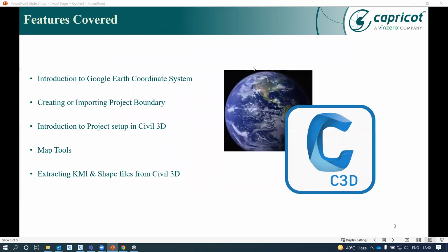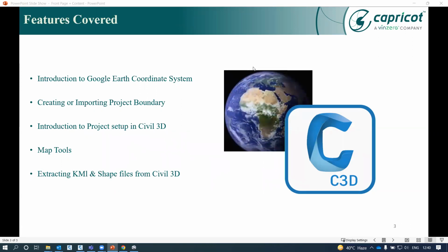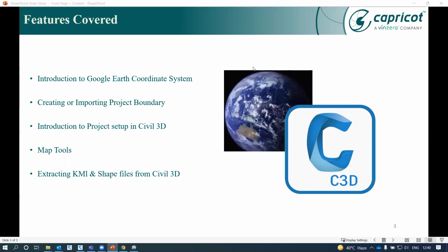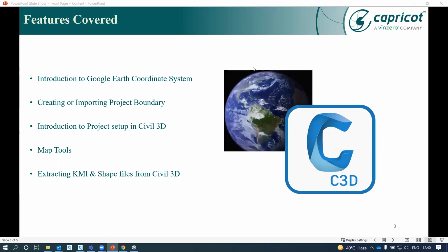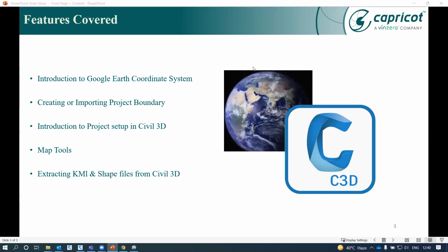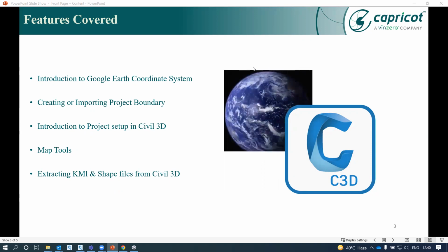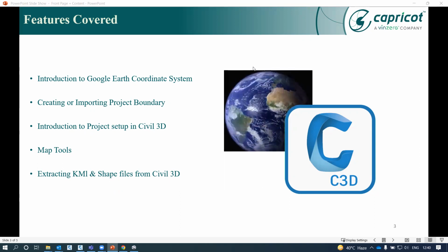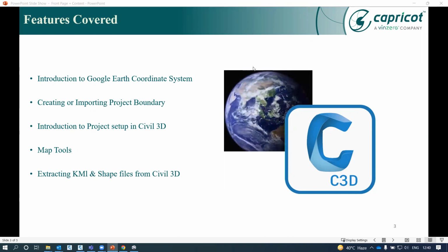In this video demonstration, I would like to cover the basic coordinate system which the entire world uses to work. Later, I would like to cover the creation of a project boundary in Google Earth, extracting the KML file from Google Earth, and importing that KML file in Civil 3D for the next workflow. I also would like to cover basic project setup in Civil 3D and importing that KML file and extracting project boundaries out of it.